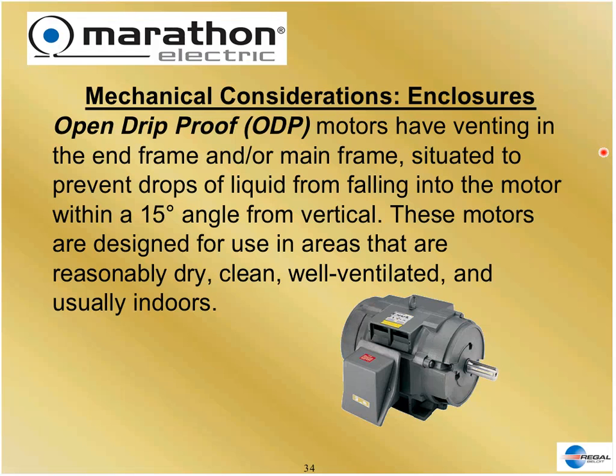We have to get the heat out of the motor somehow. The way we do it is by various enclosures. The first enclosure we want to talk about is an open. Now, motors either have openings in their frame, like this one does. You can see the openings if I slide it over here enough. It has openings, or it does not. It's either enclosed or it's not.